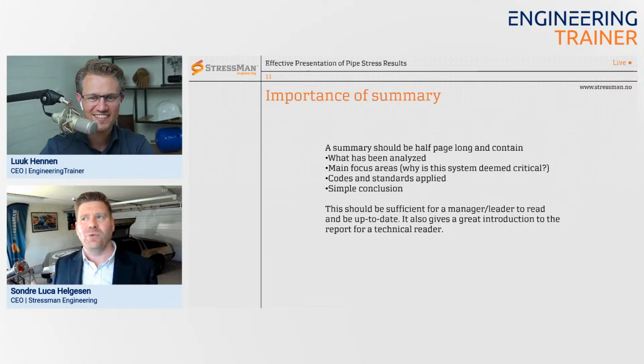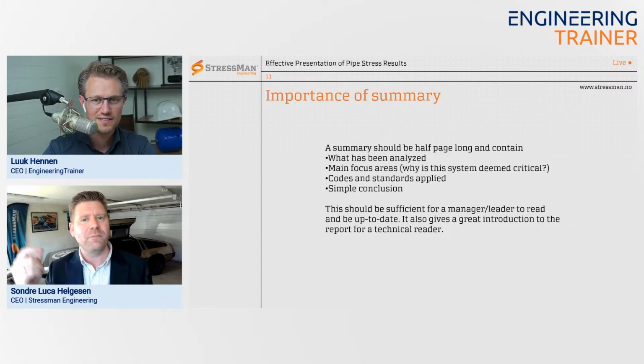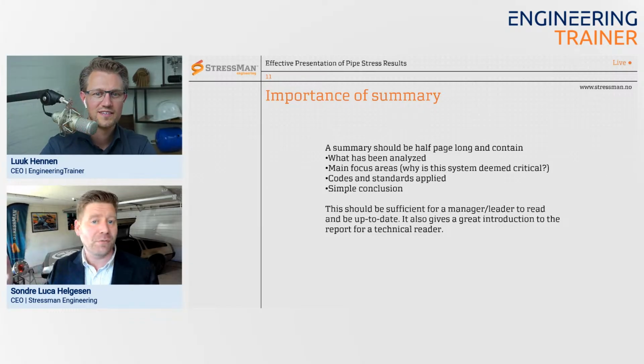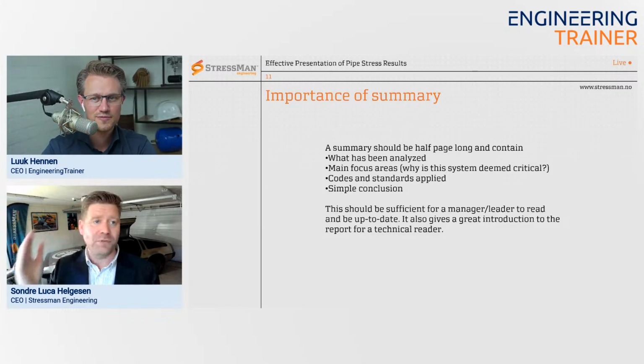Yeah. Exactly. And what happens then is, okay, can we look into, for example, flexibilities? I don't like messing around with gaps, for example, because we are not making Swiss watches here. We are making piping systems. So playing around with a 1.7 millimeter gap doesn't make sense, for example. Of course, looking at your supports near the pump, of course, you probably did that.